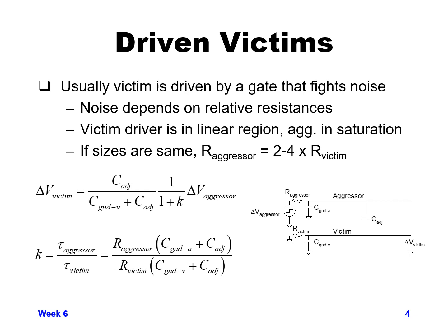The VDS across that transistor is close to 0. You've pulled the wire pretty close to ground already. So the linear region has a certain resistance to it, whereas your aggressor is in the process of switching, so it's still in the saturation region.